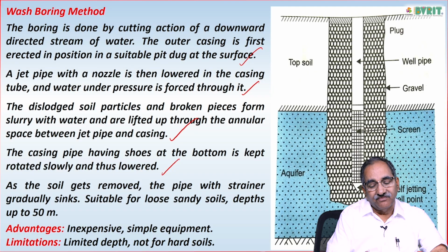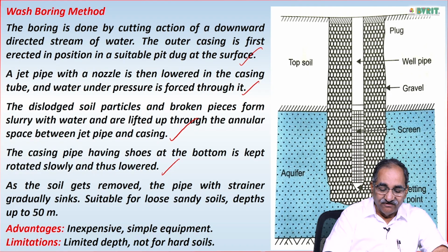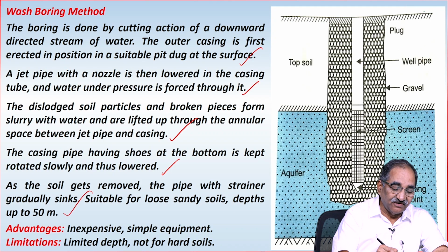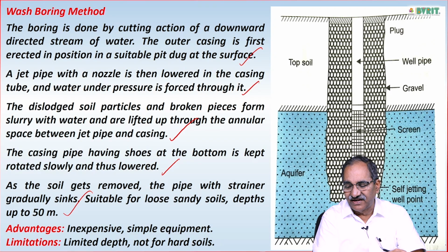The soil gets removed and the pipe with the strainer gradually goes on sinking. It is unsuitable for loose sandy soils, works for depths up to 50 meters, up to 150 feet, and cost-wise is very, very low.